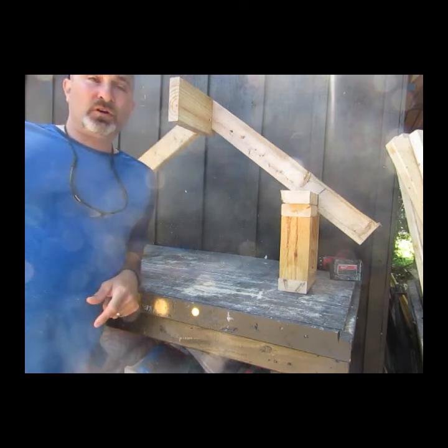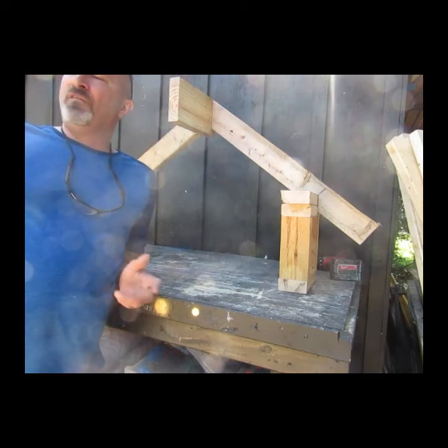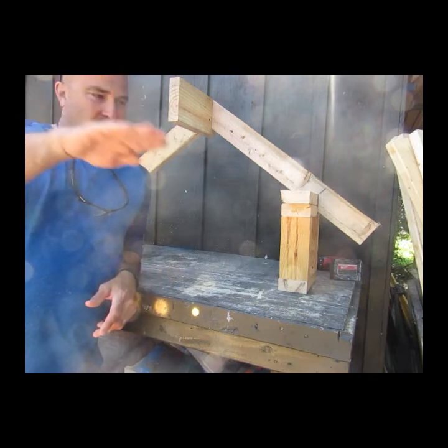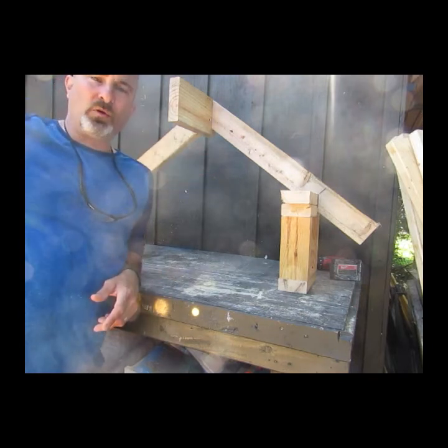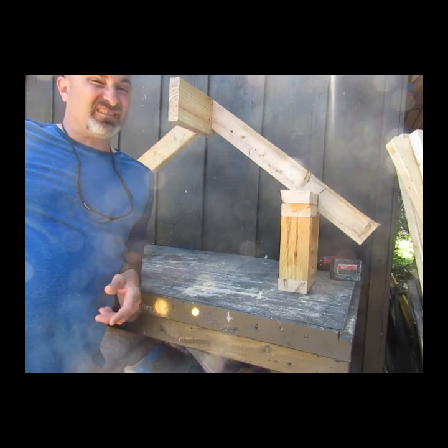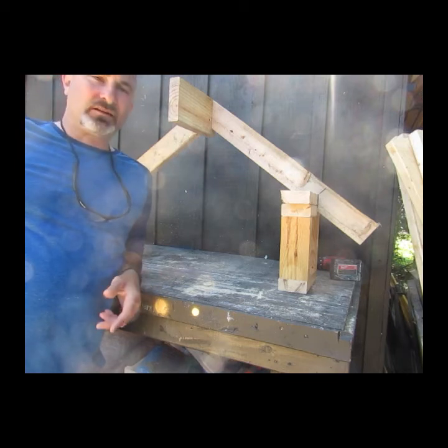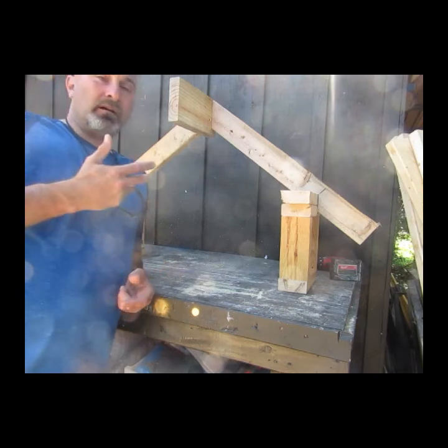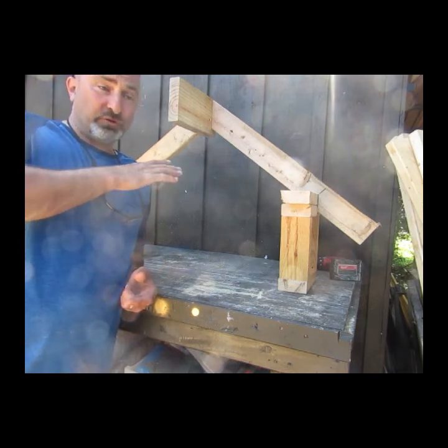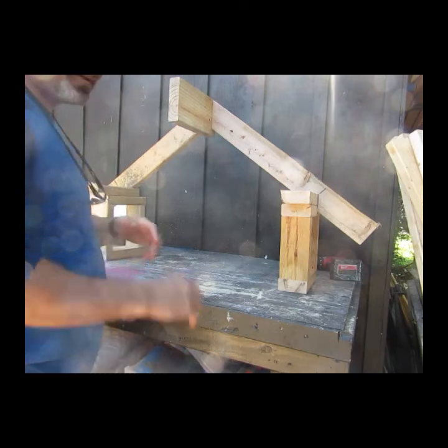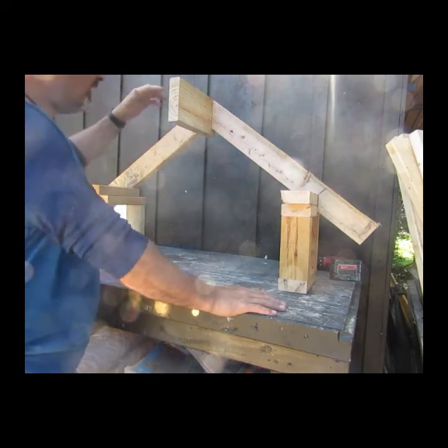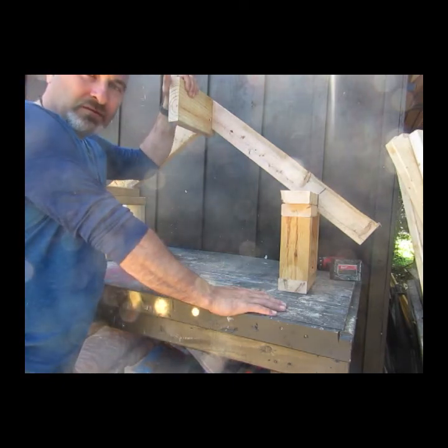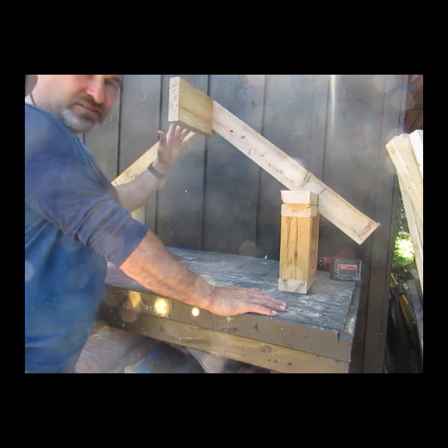Go for a ride in the country, and you'll see some farms and some barns, and they've got this huge ridge line going all the way across their barn, and over the years it's sagged. Well, they've lasted a good number of years, but they don't have the right dimensions of lumber up there to support all of that weight, especially the long spans you see barns have. So this ridge beam has to be of the right dimension in order to resist the sag.